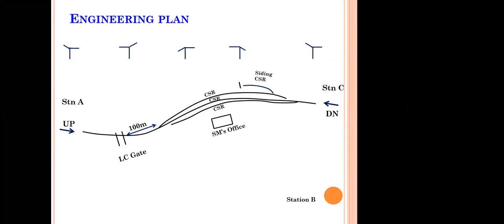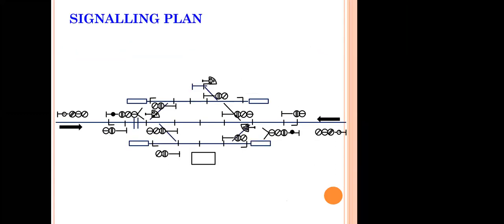However, in this course, it is a very high level course. As I said, it's a trailer course, based on which we have planned a signal interlocking plan. We have also installed here all the main signals. What are the main signals? The distance signal, home signal, and starters are the main signals. Why are they called main signals? Mainly because they deal with the train movements on the running line. We have already defined what we mean by running line in the signaling system.